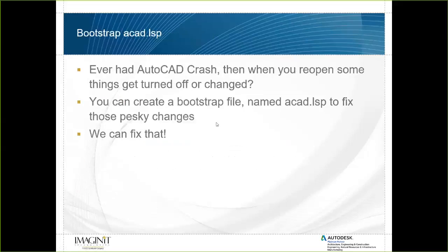Now we're going to talk about the good one. There's something you can create called a Bootstrap, and you name it acad.lsp, because most of us have run across this before. You've had AutoCAD crash, or something happen in AutoCAD, and the next time you reopen it, some things get changed. Usually the big one is FILEDIA or CMDDIA getting turned to 0 from 1, where you go to open a drawing and it opens in the command line as opposed to bringing up your dialog box.